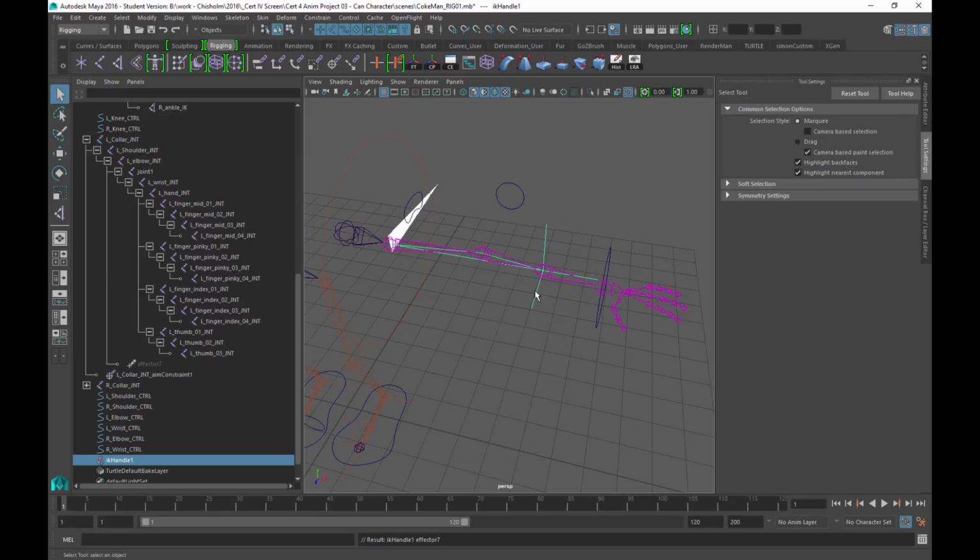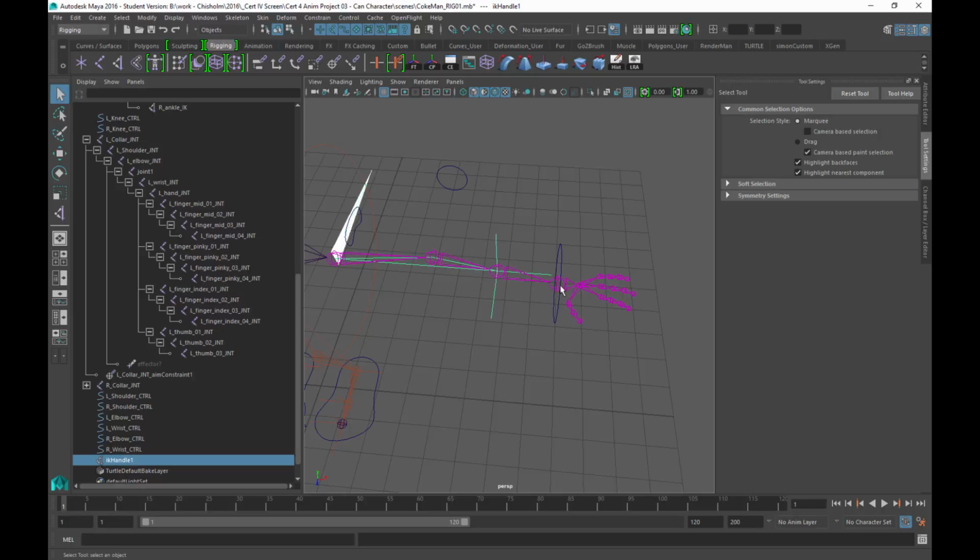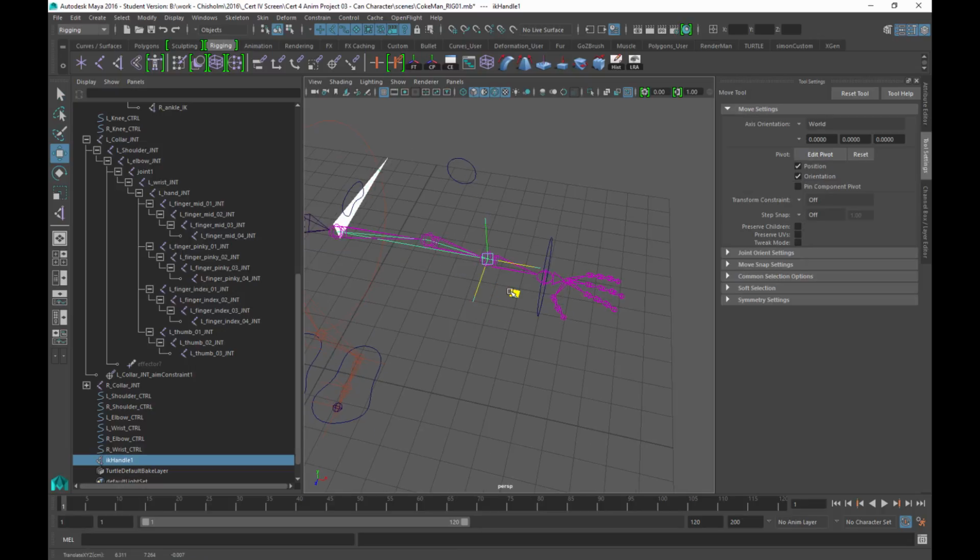The reason that we're not adding it to the wrist is that if we add it to the wrist, it will treat the forearm joint a bit like an elbow as well, and it'll cause the arm to bend at this position. So what we need to do basically is position the IK just here, and you can see that that's going to keep the forearm rigid when we move the character's arm around.